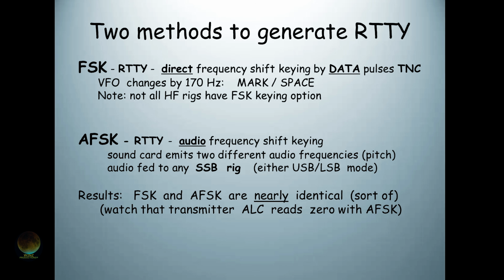So if you do that and you're on AFSK RTTY, you want to be sure the other sideband, the lower sideband, doesn't come out. But that's true for voice too. And you want to be sure the carrier gets annihilated in the radio. The carrier should be subdued by 30, 40, 50 dB. So what you're transmitting is just 2 RF signals. At the other end, for someone listening to a RTTY contact, you can't hear the difference. You can't tell how I'm generating RTTY.